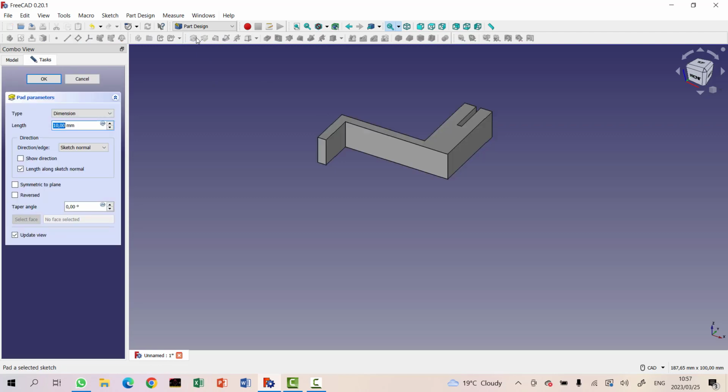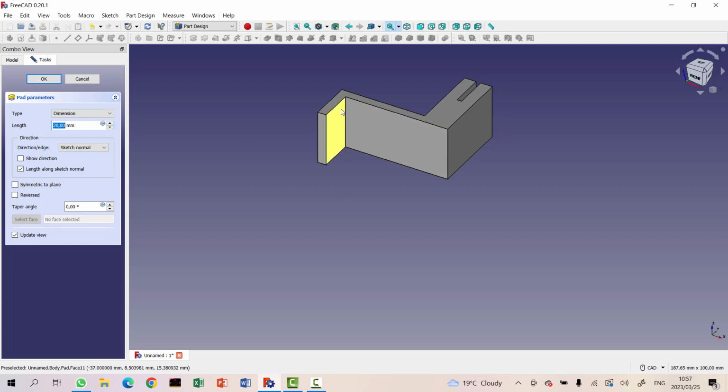That's what it's going to look like. It's a little bit thick there, but it's okay. It makes it stronger. It doesn't really matter that much. So I'm going to make it a whole lot wider, like 20. 20 should work just fine. And then I want to put holes in there. I want holes in there for the screws to go in through the extrusion.